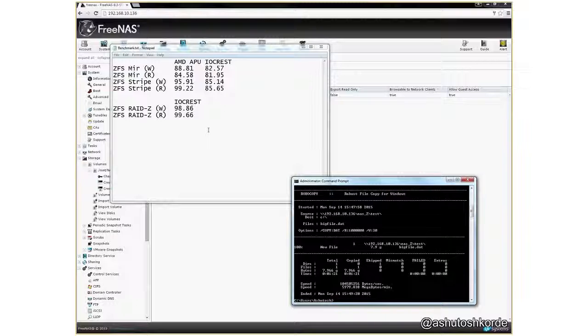One thing I failed to mention in this whole video is that we are using regular DDR3 RAM and not ECC RAM. The problem with using regular DDR3 RAM in such NAS builds is that if there is memory corruption on the DDR chip, there is no way for the NAS to detect it.